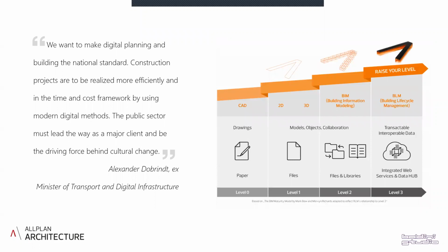There are several levels of BIM implementation. Level 0 represents generation of CAD documentation for 3D object description. Level 1 represents creation of 3D models from which the 2D documentation is generated. Level 2 represents the collaboration between the project members based on a unique standardized format of exchange, IFC, which enables conversion, or so-called translation, of digital models to other software. Level 3 represents an upgrade of BIM level 2. It's based on active project sharing throughout the entire project lifecycle while working online, so-called working in the cloud.